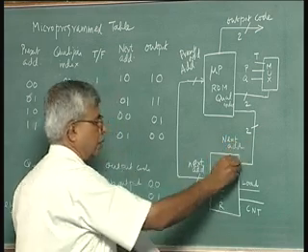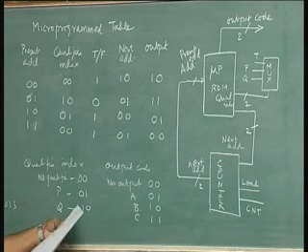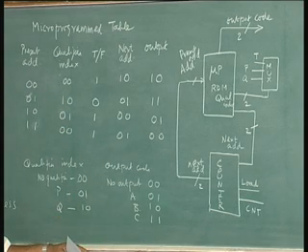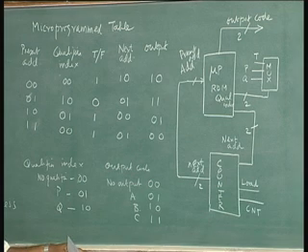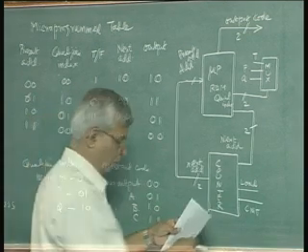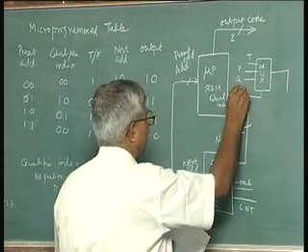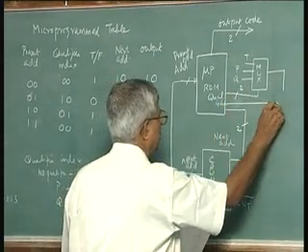Next address gets loaded or it is counted. How will you decide that? That will be decided based on the bit being true or false. That means I need to have a comparator. I need to have an exclusive NOR gate, wherein I take this value from the multiplexer and compare it with this value, which is the true false bit.